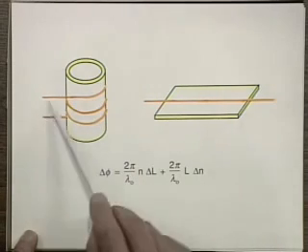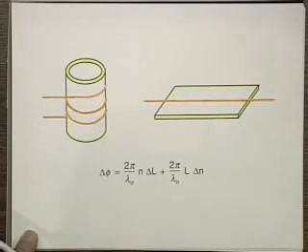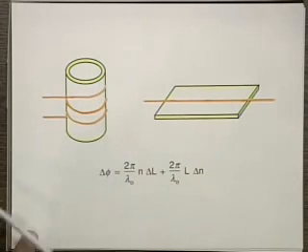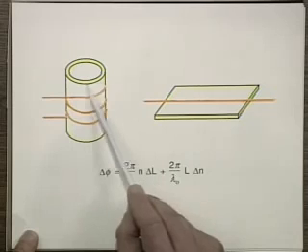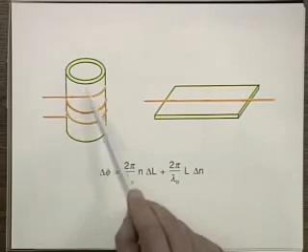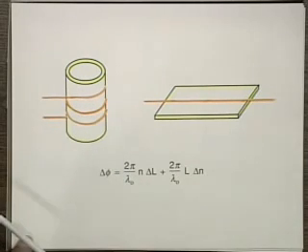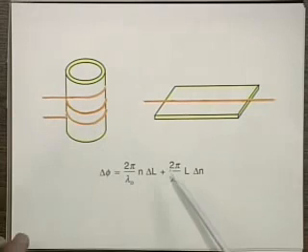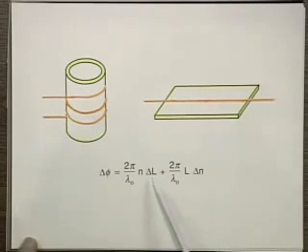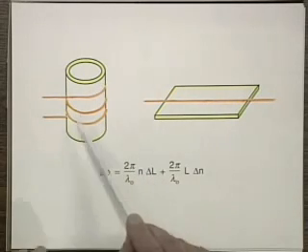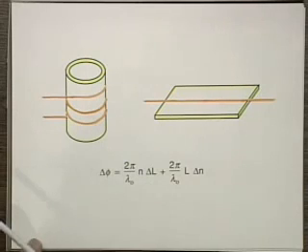One way of doing this is to take the fiber and wrap it around a piezoelectric crystal. If we put a voltage between the inside and the outer surfaces of this crystal, then we can change the diameter of this cylinder, and in this way we can change the physical length of the fiber, or by stressing it, we could also change the index. But whatever, you get a change in the phase of the light propagating by applying a voltage, either a DC voltage or a sinusoidal voltage, to this piezoelectric cylinder.